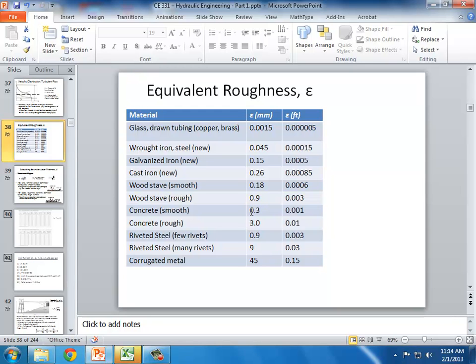The reason I'm doing this is I'm going to find the relative ratio so that I can have in mind my first guess of F. Since it's times 12 inches and divided by 12, our K sub S over D for the 8-inch pipe will be this, and the K sub S over D for the 12-inch pipe is just going to be